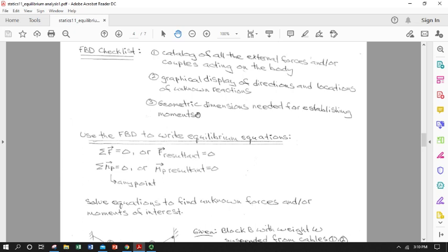You may just be able to go with orientations of forces and adding them all up, resolve them in the orthogonal directions and get your force balance. But because moment as a result of forces is of course r cross F, you need the dimensions of the part to get r.